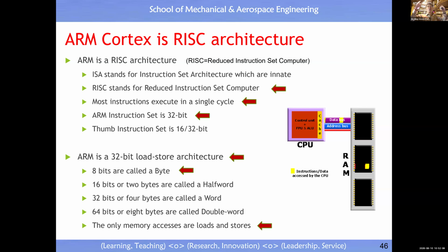By now, just remember, internally 32 bits in one cycle flow in, flow out, 4 bytes. But between the microcontroller and the external device, at one time the maximum is 8 bits. If you have more than 8 bits, then you have multiple cycles: 1 byte, second byte, third byte, etc.